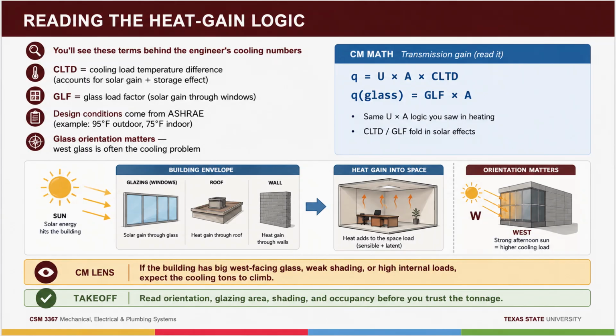We've built the load in BTUs per hour: envelope, solar, people, lights, plugs, outdoor air. Now the unit the entire industry actually talks in, the ton. 1 ton of cooling equals 12,000 BTUs per hour. Where's that from? The ice trade. The cooling delivered by melting 1 ton of ice over 24 hours. The ice wagons are long gone. The unit stuck. A 5-ton rooftop unit removes 60,000 BTUs per hour. A 400-ton chiller plant for 0.8 million.